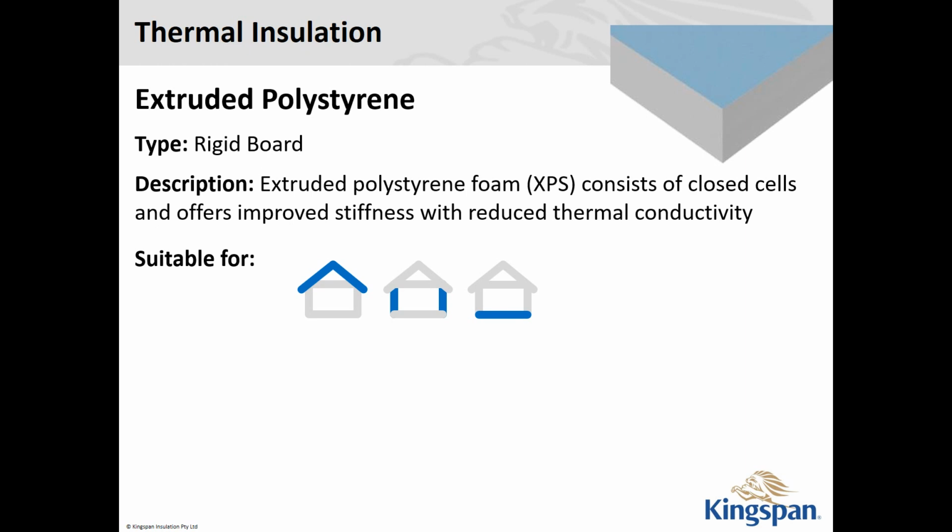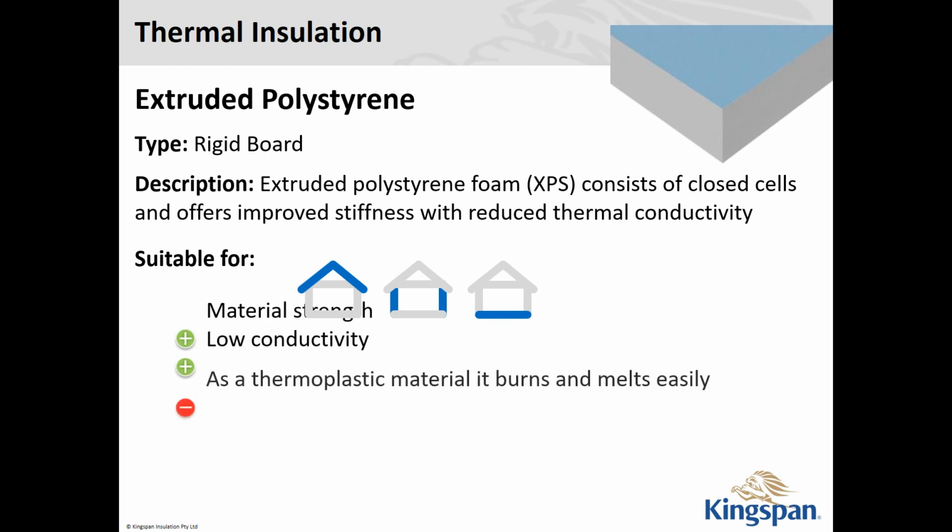As you know, anything that's a foam, especially a polystyrene, you put a flame to it, or even 90 degrees Celsius, it starts to melt a little and lose structure, and if it had a naked flame to it, it can catch light and combust quite easily. But it does get used quite a fair bit in your roof, walls, and floor. In the past, like I said, that is starting to change, but it has a low conductivity.